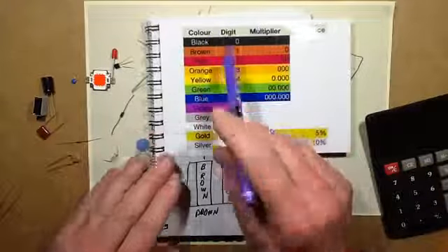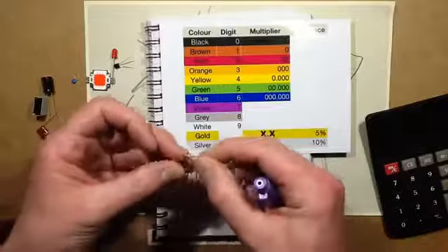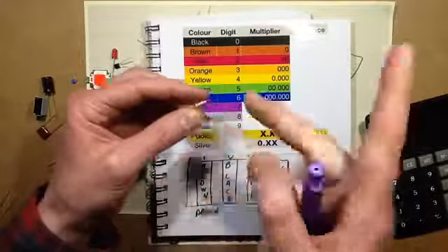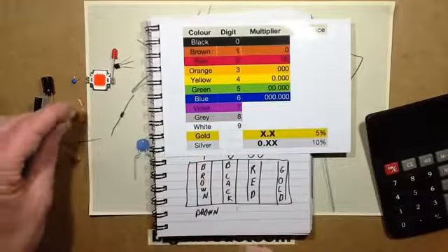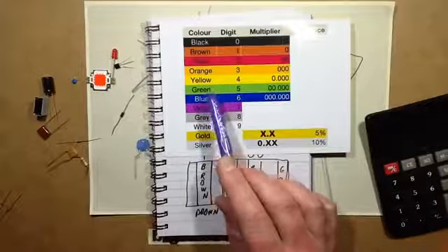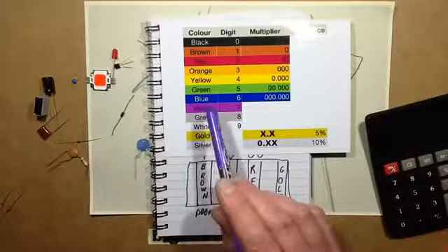And after you've been using resistors and reading the colour codes for a while, you'll just look at a resistor and go, 1K. Just look at it and instantly know the value. It's how it is. The same colour code is sometimes used on older capacitors, and it's still used on inductors, which look very much like resistors.